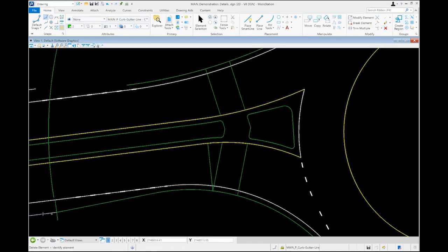And so now I've got the end of this taper right at that 100-foot offset from the ICD. And if I just do a double check to make sure I ended up with right around that 8-to-1 taper, there's my tie-in point almost exactly at that 40-foot distance.